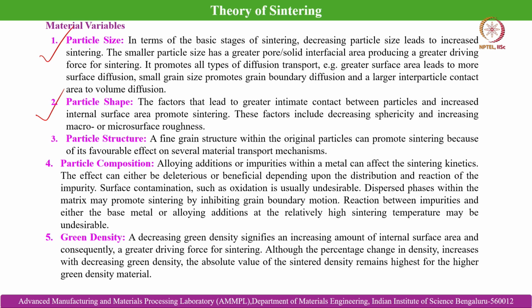So that is what I mean. If you recall, we have discussed earlier the necessity of achieving spheroidal powder particles, and if in spite of that we get irregular powder particles, we can achieve greater interlocking during green compact preparation, and thereby higher green density. But during sintering, the connection is not as good as we can achieve in the case of spheroidal powder particles.